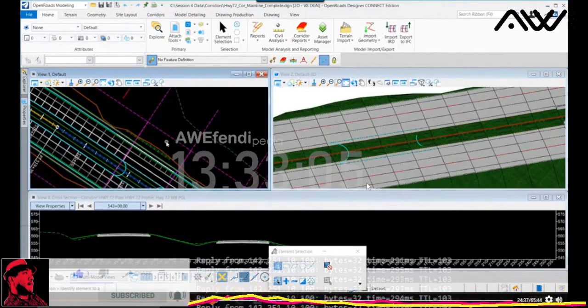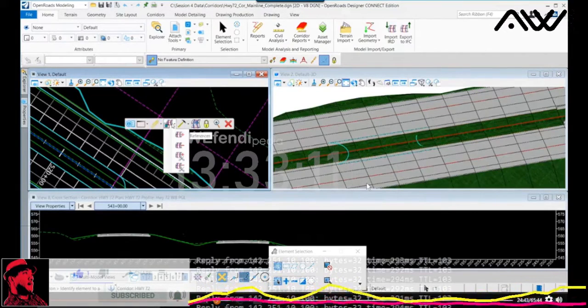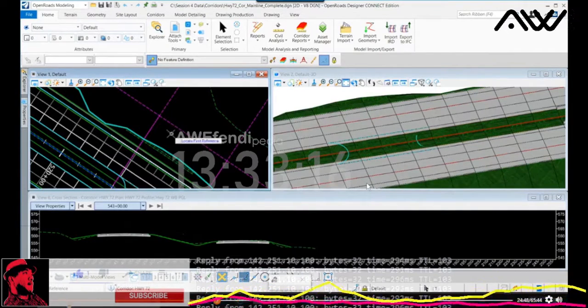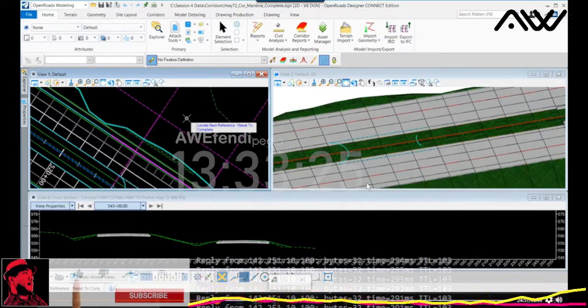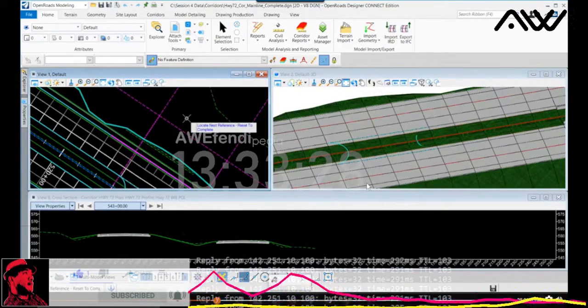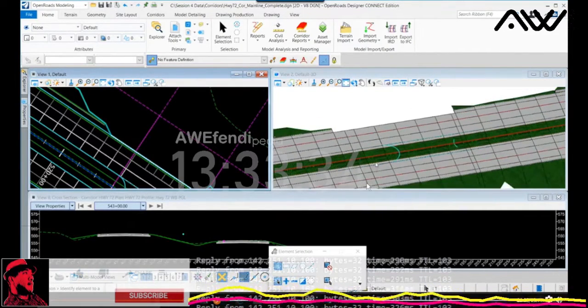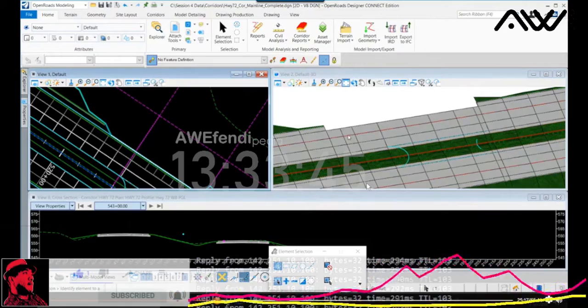Now, to activate that, we're going to select the roadway corridor itself. We're going to add that match line string as a corridor reference. So I'll select that button, go out, select the element itself, and then right click. The corridor is going to reprocess now that that element's been added as a reference into that corridor, and you'll see what the results are. Based off of nothing more than that line with a specific feature definition and the template looking for that feature definition, we've now turned off that area where our intersection is going to be.